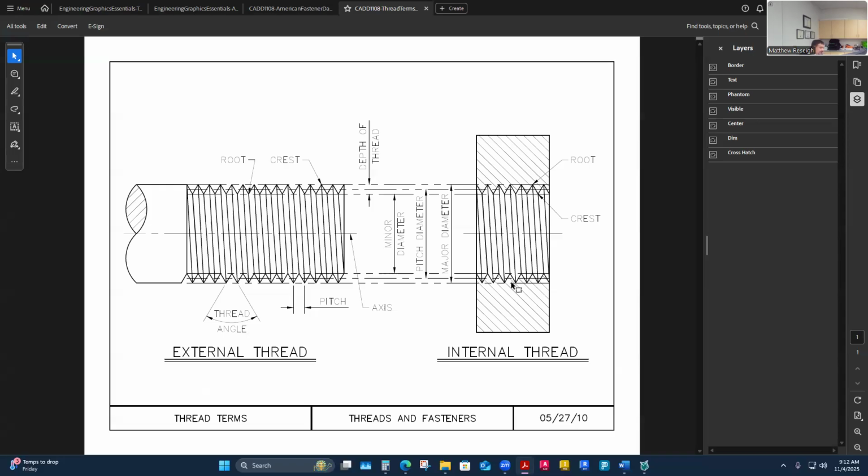And you can do this from your home. You can buy a tap set and drill a hole with a drill, and then cut the threads in it yourself by hand. This is something that I sometimes have to do at home, or clean up threads at home. So you sometimes have to know how to put the maximum material condition in that hole so that I can cut the threads out and actually have the engineered design intent for that fastener.